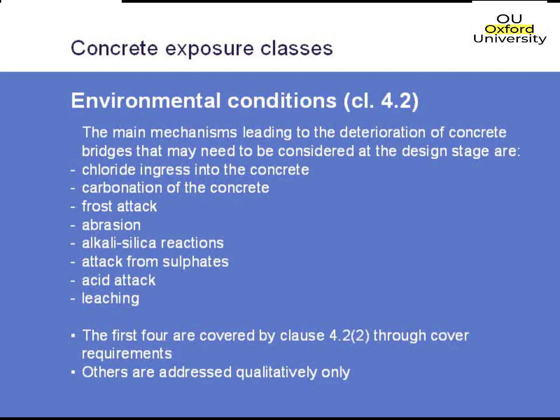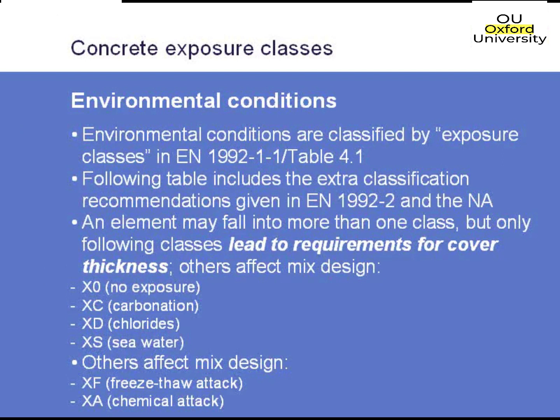The cover thickness which is selected is dependent on the concrete exposure classes, and these exposure classes are covered in Table 4.1 of Eurocode 2 Part 1. These classes will be quite familiar to you because they are also the ones that are given in BS 8500, which were actually based on the Eurocode ones. So there's a sort of overlap in that.